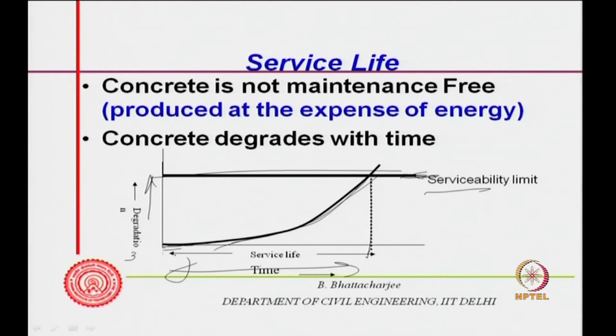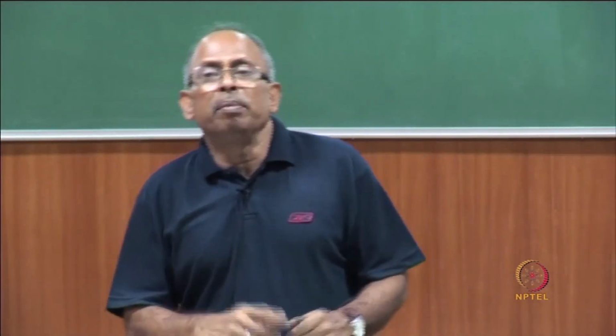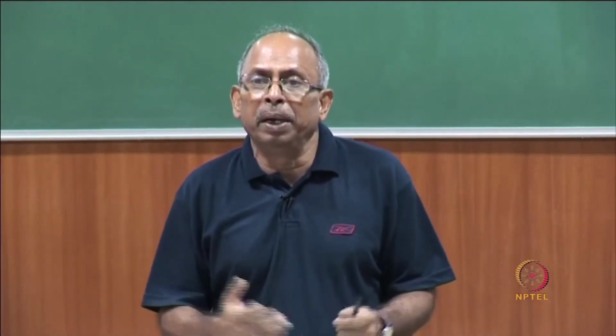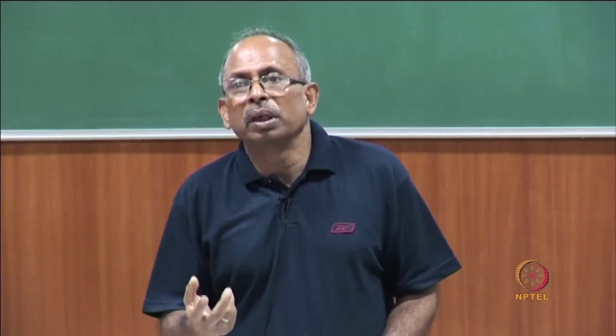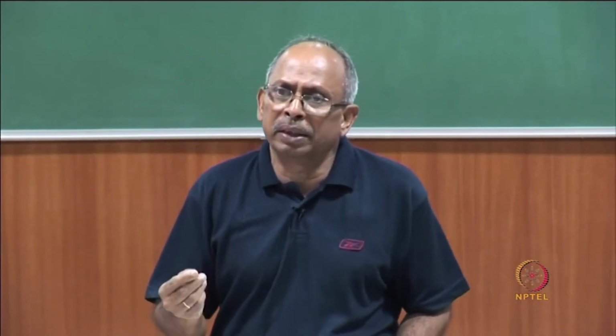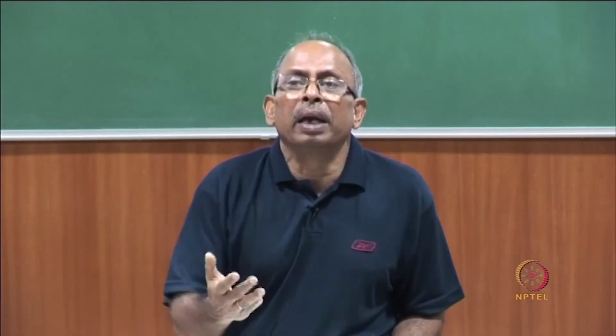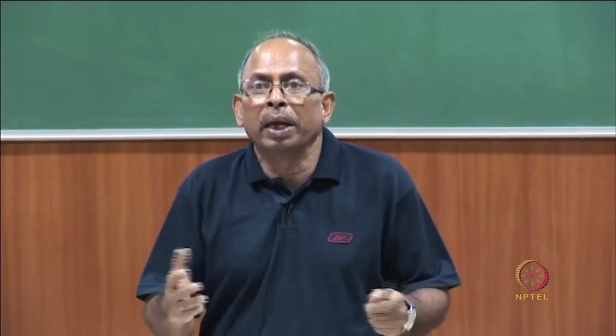Most degradation does not lead to immediate failure, and when we talk of service life, we are talking with respect to an element. I am talking in the context of concrete. You can imagine even in a steel truss bridge, an element shows some cracking because of fatigue, maybe over the years of reversal of stresses, it shows a fatigue fracture. You remove that element, put in another one, the bridge is still okay, it can last for a longer